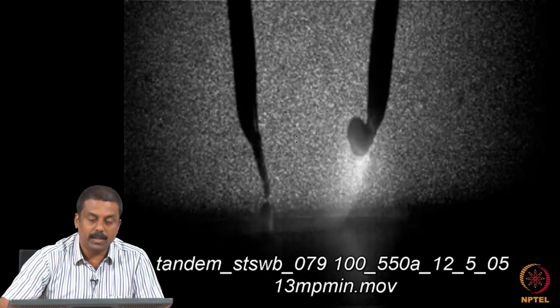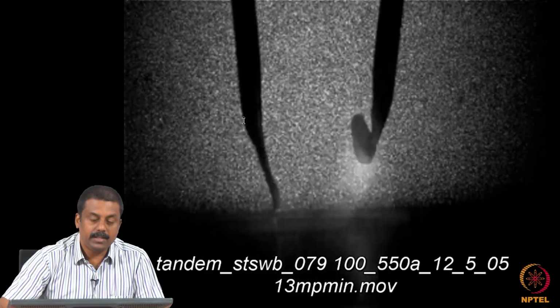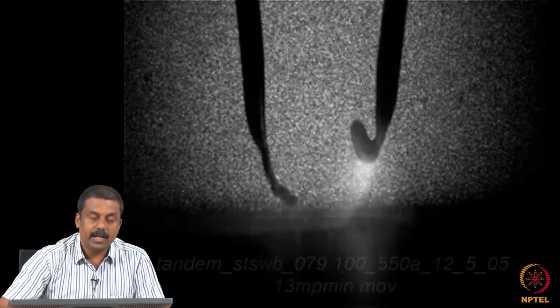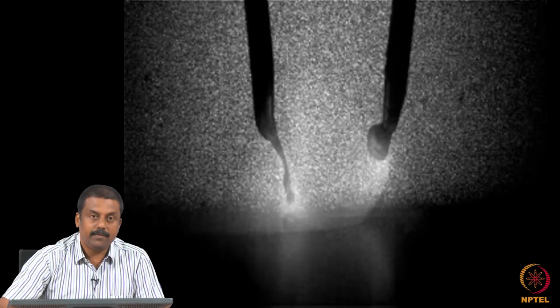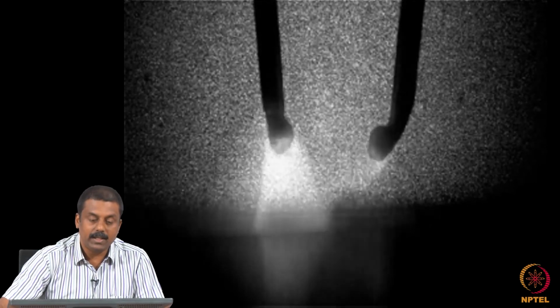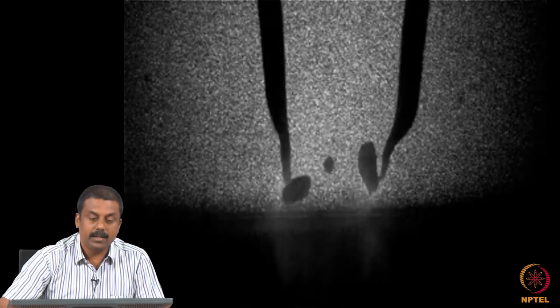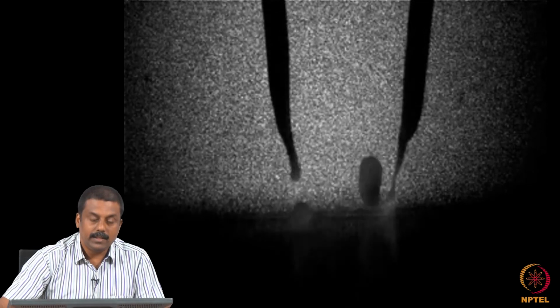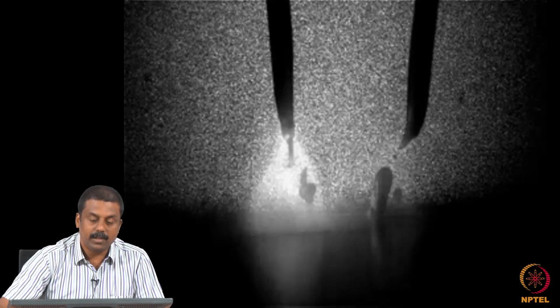The important characteristics of this process are controlled by the current, the amperage we send, the shielding gas we use, as well as the melting characteristic of the electrode, which is also controlled by the current, as well as the diameter and the stick out length, the distance between the contact tip and the workpiece.